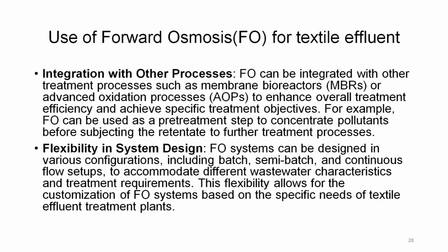Integrating with other processes. FO can be integrated with other treatment processes such as membrane bioreactors (MBRs) or advanced oxidation processes (AOPs) to enhance overall treatment efficiency and achieve specific treatment objectives. For example, FO can be used as a treatment step to concentrate pollutants before subjecting the retentate to further treatment processes.